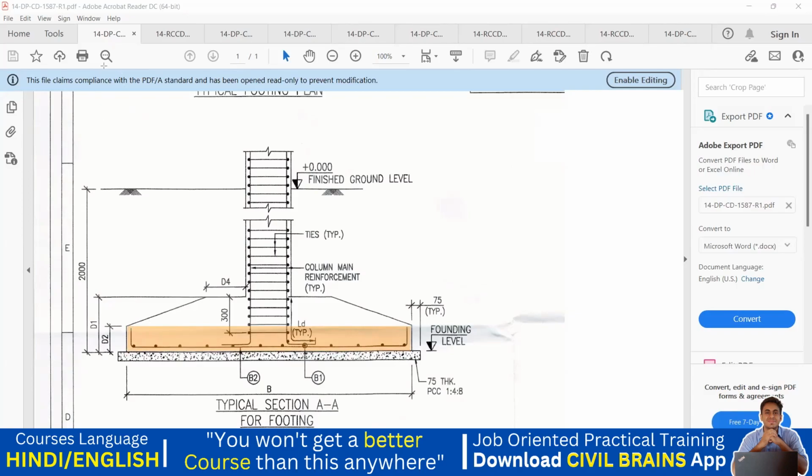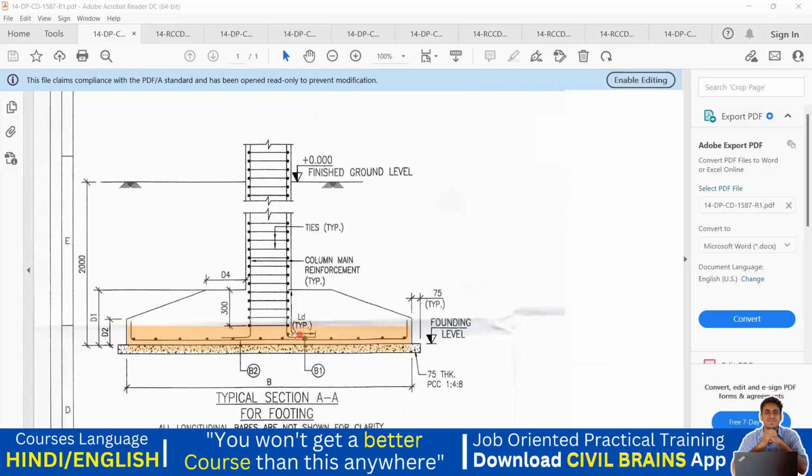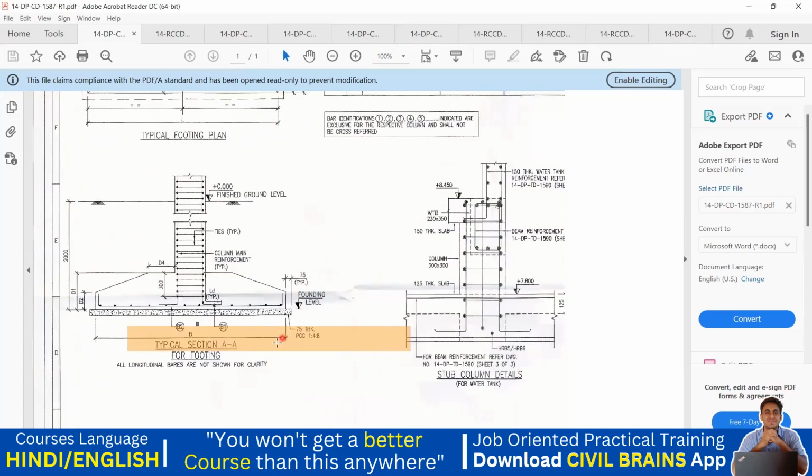So how do you find this area? Very simple. How do you find the distance from here to here? D1 minus D2 is going to give me this distance. Got it? And now they have mentioned all these things, like D1 is this complete depth, D2 is this depth. Then what is D4? D4 is from column outer to this part. This is D4. All those things will be written in the drawing. Based on that, we have to do the execution. Great. So we understood the footing layout now.